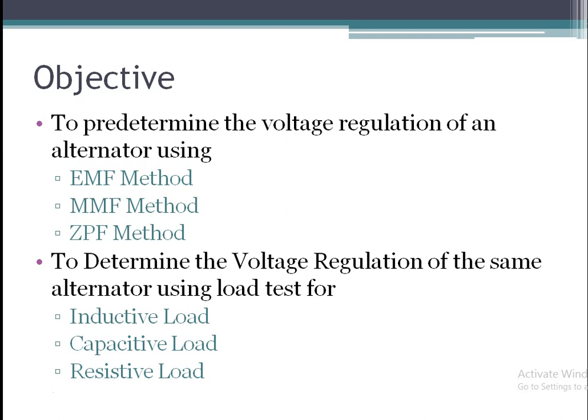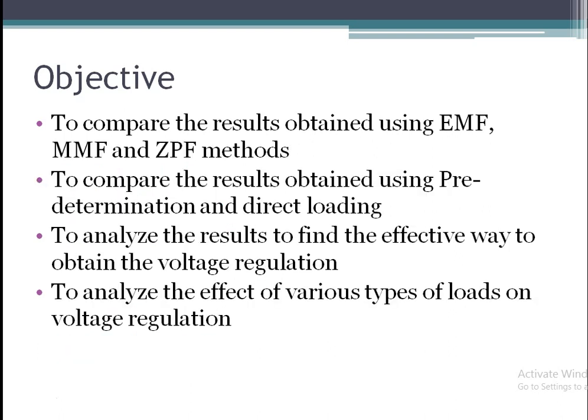In the case of the load test, you are again assigned to carry out the same experiment with three types of loads. One is the resistive load, the other is the capacitive load, and again you have to add an inductive load to the same circuit, same alternator, and find the effect on voltage regulation for the inductive load also.